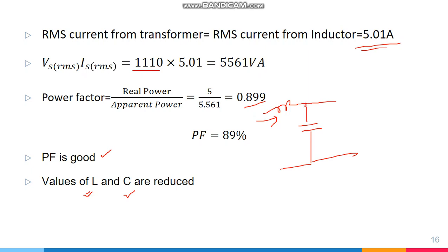The issue we were discussing, that inductive filtering is not suitable for a regulated power supply, was due to the spikes that may appear across the inductor. But here we have a capacitor at the output, so it will be able to supply or absorb any kind of surges that appear across the output load. So this is very beneficial for us.